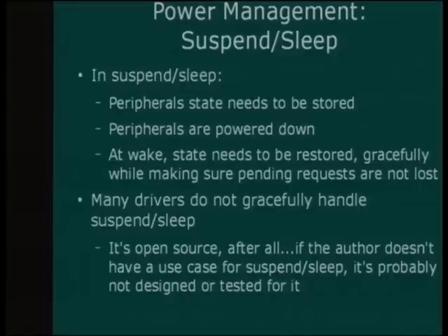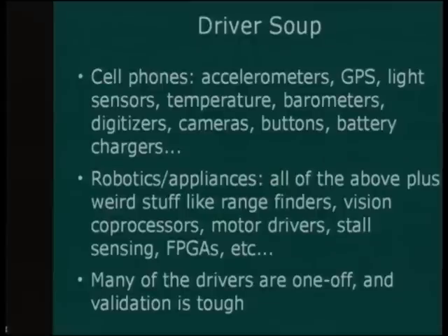Suspend and sleep is painful. One of the troubles of being open source and embedded is that people write a driver, they check it in, it's great, but they didn't include suspend and sleep support, whoever it is. This is a very, very frequent problem I have. So we end up taking drivers for different elements, and we have to refactor them to deal with the fact that sometimes you want to actually turn off the peripheral while Linux is still on, power on the peripheral later, restore its state, and have that all work correctly.